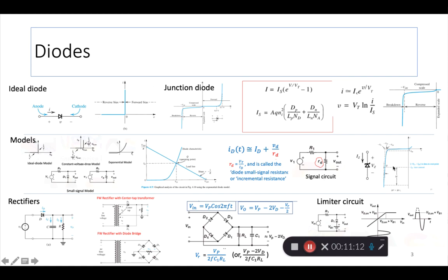One more time, on the reverse side, we were introduced to the idea of the Zener diode. A Zener diode is a special diode that is designed just to work in the reverse direction under breakdown conditions mostly. And the applied voltage is always the opposite, right? Because we are working in the reverse direction, so the anode is negative and the cathode is positive, and we are working on this side of the diode characteristic.